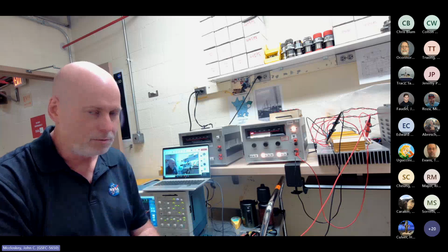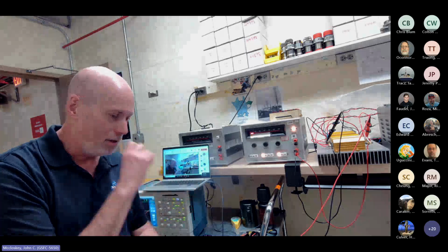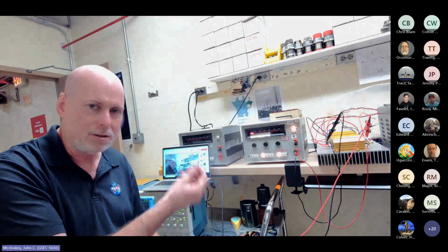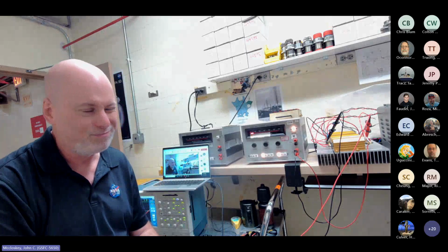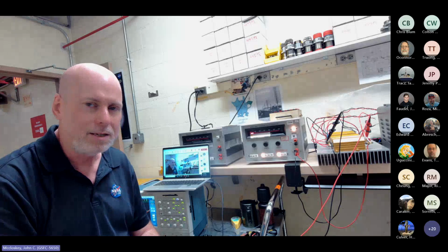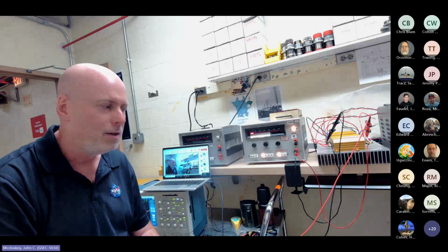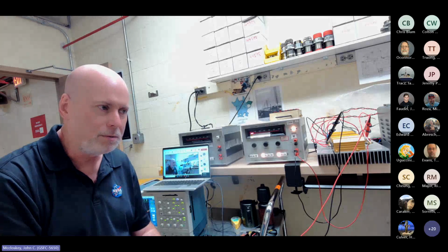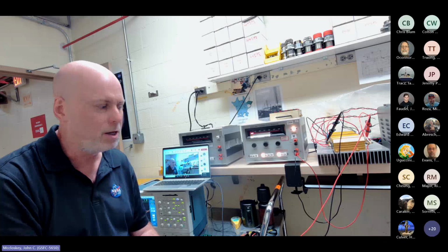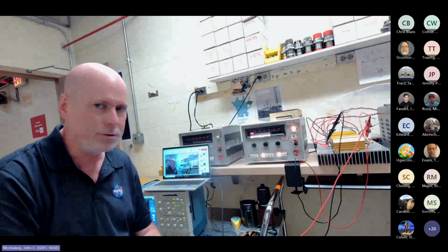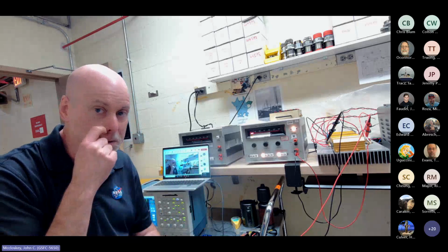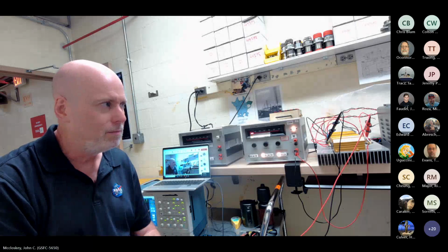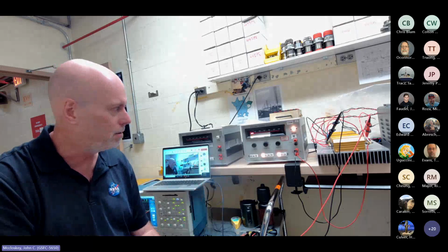But certainly turn-offs were absolutely benign. We never had the scope trigger once. And if the worst case is a 30 amp transient pulling the bus potential down by half a volt, that seems pretty inconsequential too. So that's where doing that upfront homework to understand the power distribution scheme, and to determine whether these transients are even something you're likely to be concerned about, can basically render this whole test method rather moot.